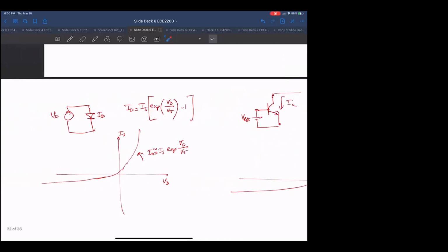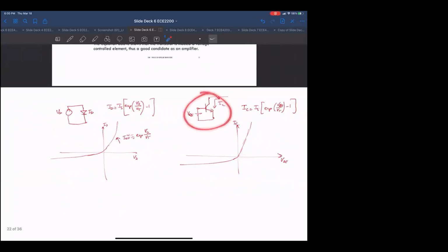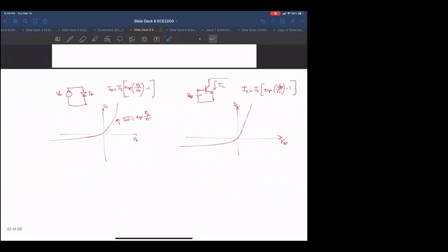Whereas in a diode, the voltage is connected across the device, so if you want to look at the output, you've got to do something else with it to get a working device. This is what makes it really powerful: the separation of the input, which is a controlling signal, from the output, which is what you're changing, which in this case is a current. It's always a current, whether it's a bipolar transistor or a MOS transistor.